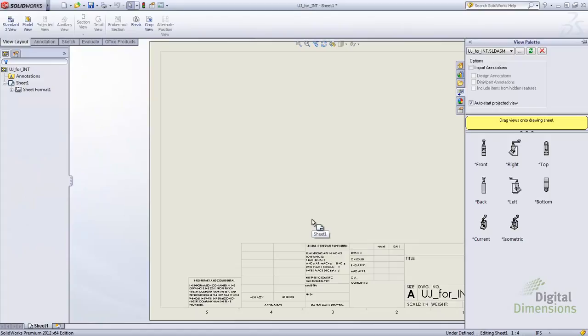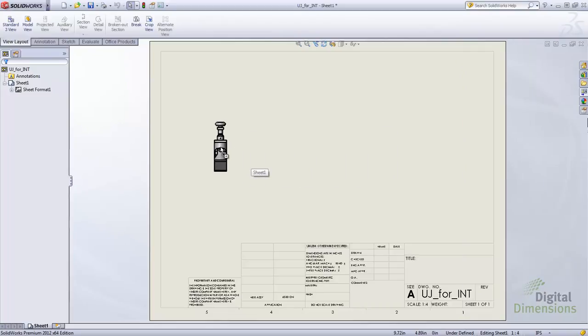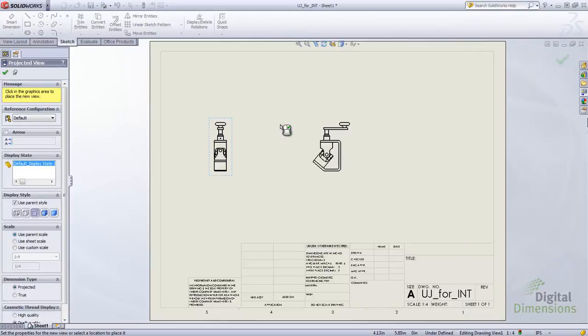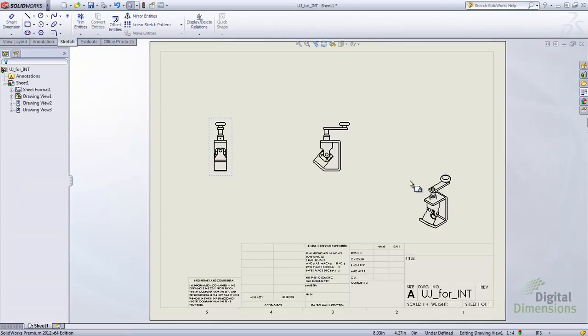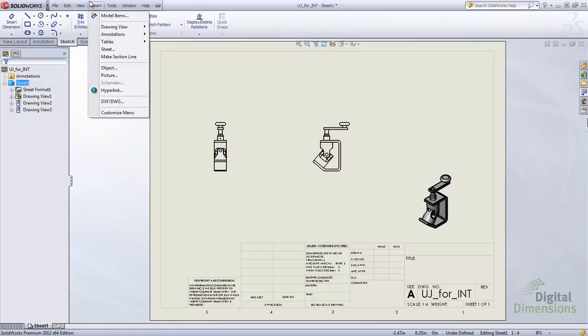We're going to go in and generate a new drawing, and we can click and drag our different model views, as well as change up display styles, add dimensions, callouts, bill of materials, etc. To illustrate bringing in a bill of materials for a future version file, the same workflow applies.